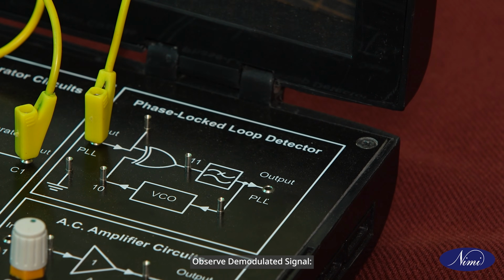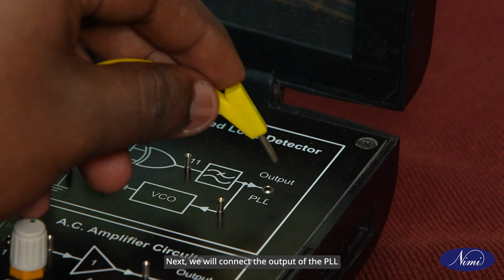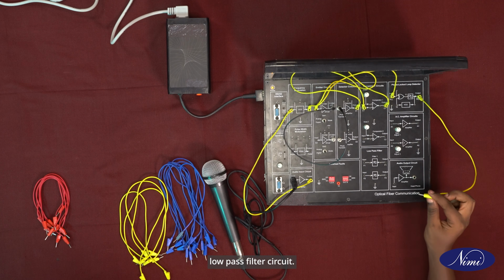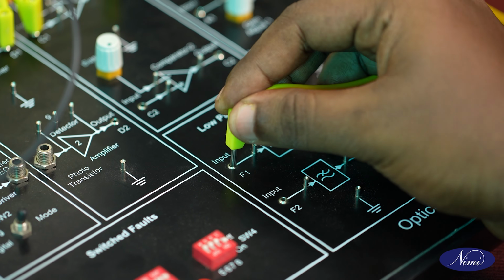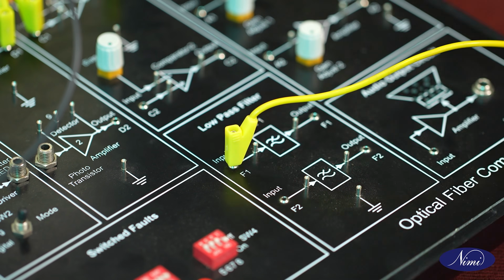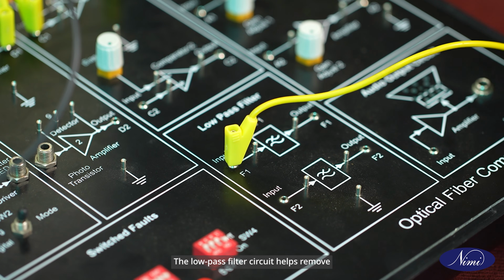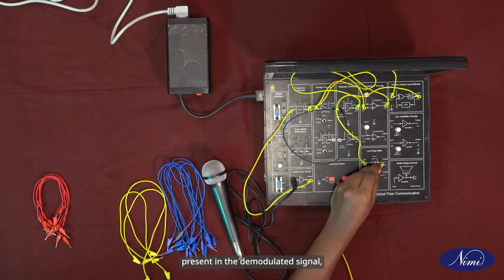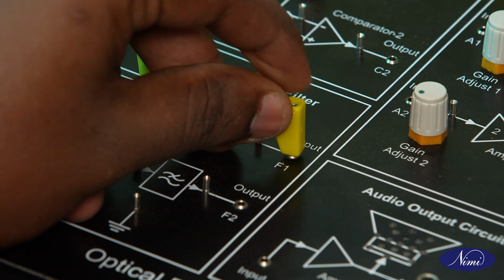Observe demodulated signal. Next, we will connect the output of the PLL detector to the input of the low-pass filter circuit. The low-pass filter circuit helps remove any high-frequency noise or interference present in the demodulated signal.